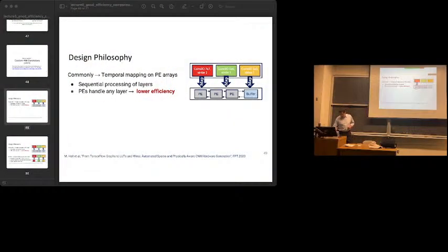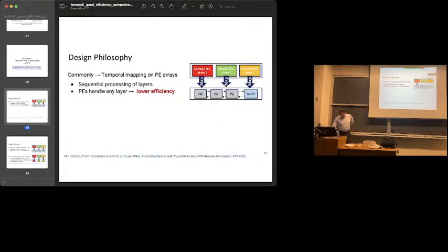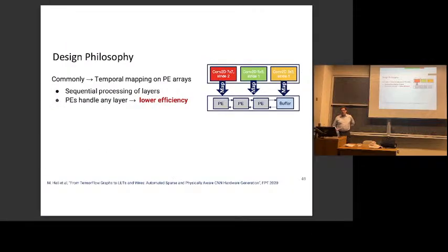So you build a whole bunch of these processing elements, they're communicating together, they've got some buffer RAM, and you take maybe the first layer in your neural network, say a two-dimensional convolution with a 7x7 filter size, and stride 2, which means you move the filter over 2 pixels every time you complete one output. And you basically map that layer using these PEs. The control logic sets their muxing, etc., so that they implement what this convolution needs.